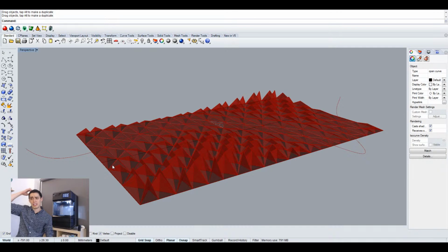So this is basically a bunch of pyramids, kind of a diamond shape texture, similar to what you would see, let's say, on dumbbells or on the grip surface of a bicycle handlebar, right? And here's where it all connects back to product development and why I started with this a little bit more abstract example. What I'm trying to show you is how to create textures for some of your 3D printed parts, right? So perhaps you're modeling, as I said, the bicycle handlebar and you want to add some grip texture to it, or you're modeling the pedals on that bike, or you're modeling, let's say, kitchen utensils, and you want a section of those utensils to have a texture. This is where this becomes really handy, just to add some extra level of detail.